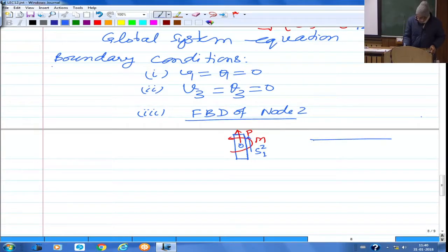So if you look at the element itself, the second element, on this side, you would have shown the shear force on the left end of this element, which is the first node of the second element, like this. The bending moment you would have shown as the bending moment here at the first node of the second element, like this. So the opposite of that is shown on this face, because this face has the outward normal along negative x. These are shown about and along the negative coordinate direction. The opposite of that is shown here.